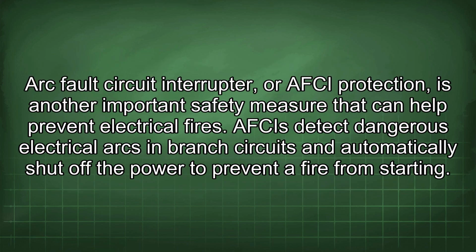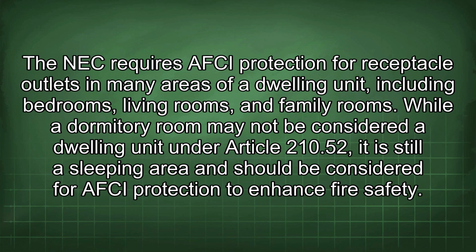Arc fault circuit interrupter, or AFCI protection, is another important safety measure that can help prevent electrical fires. AFCIs detect dangerous electrical arcs in branch circuits and automatically shut off the power to prevent a fire from starting. The NEC requires AFCI protection for receptacle outlets in many areas of a dwelling unit, including bedrooms, living rooms, and family rooms. While a dormitory room may not be considered a dwelling unit under Article 210.52, it is still a sleeping area and should be considered for AFCI protection to enhance fire safety.